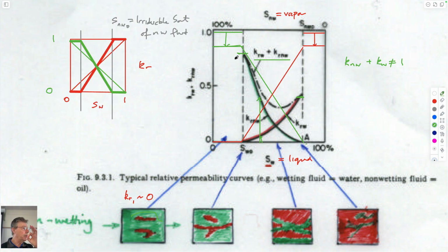And if you think about a pipe with a large diameter, it has a larger ability to transmit fluid at a faster velocity, faster volumetric flow rate than if you have ones with smaller diameters. And so the fact that the large pores saturate first with the non-wetting fluid is why this peak here is higher than this peak here, and that they don't add to 1.